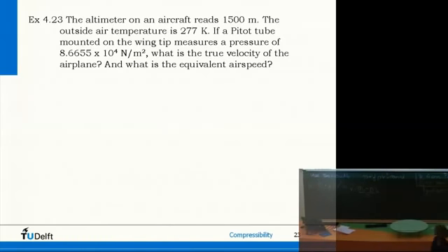Equation of state. Yes, very good point, because the temperature is given, right? So you might be tempted to look in Appendix A for the density as well, but we have here more information. So the more actual information you have, you should use it. And why is the temperature given here? Temperature is much easier to measure. How do you measure densities? It's very hard, but temperatures are always monitored, so always measured. So the temperature is given, so we find rho from the equation of state.